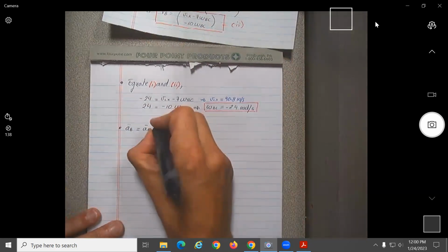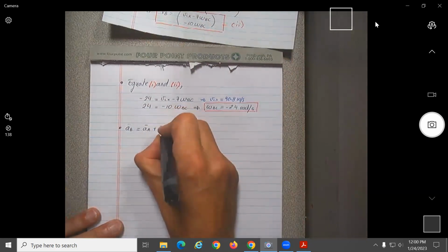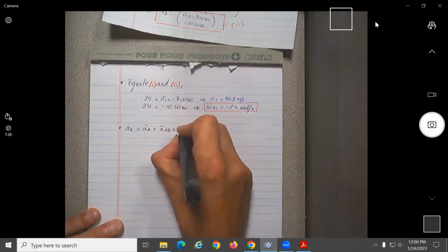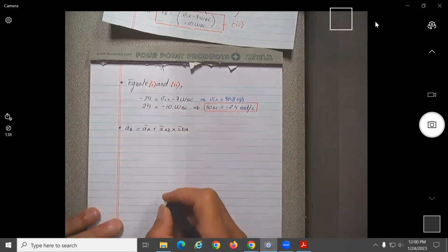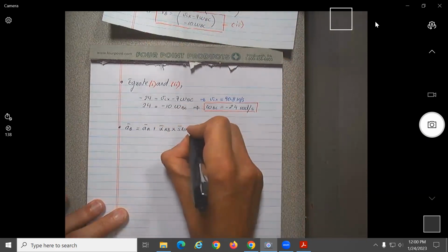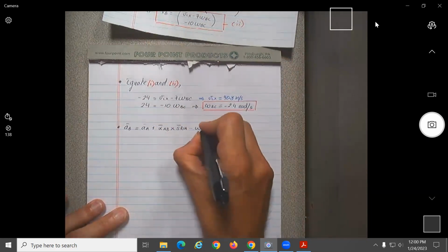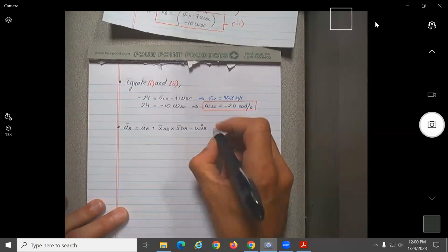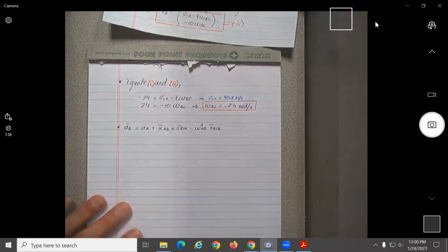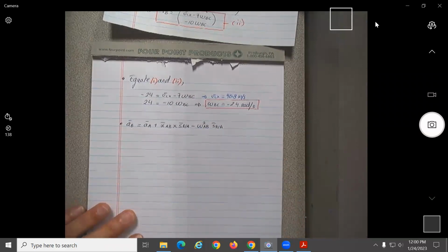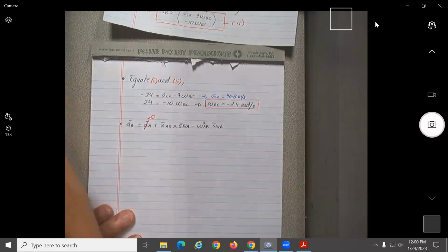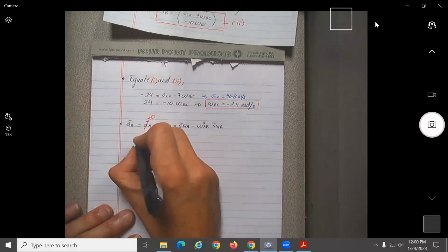So we get acceleration of A plus what? Alpha AB cross S of B with respect to A. Which term is this one? The tangential or the normal? This is the tangential. The next one, omega squared, will be the normal, no? It is important that you make the difference between each one of the terms. What is the acceleration of A? 0. So again, cross product.